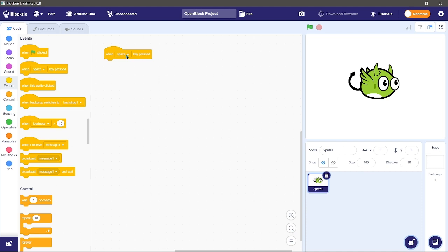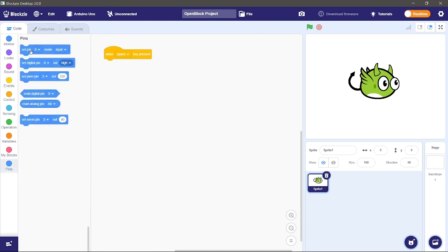Now the 7 segment means it has 7 different segments, and all the 7 segments are going to perform some indication application. So on the 7 segment we are going to have our output, hence all the 7 segments are going to behave as an output device. From the pins category of the block programming palette of Arduino, now select one block which is set pin 0 and mode. Here we require more blocks, 8 blocks, 7 for the 7 different sections and